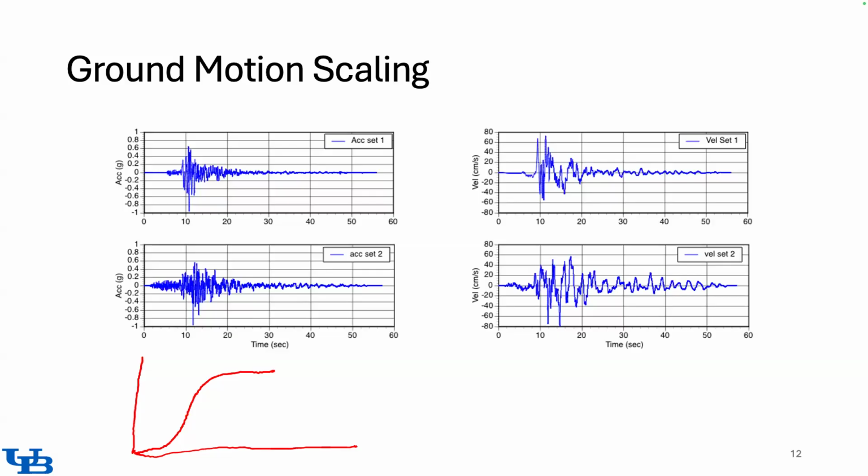One more thing. All of these things that we're discussing apply if our structure is mostly sensitive to acceleration in the horizontal component. In the vertical component, the P wave may actually have the largest amplitude, but typically for regular structures, the inertial loading on the horizontal component is more important, because in the vertical you have already designed for the gravity load, and you don't really change it.